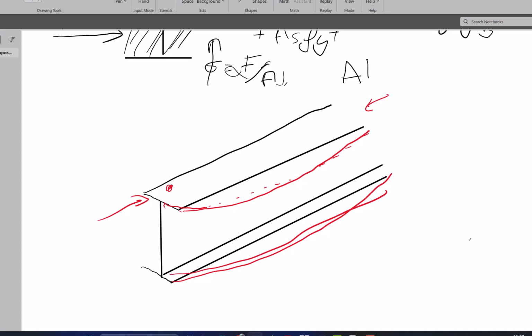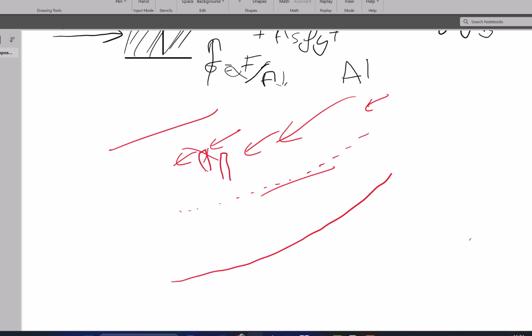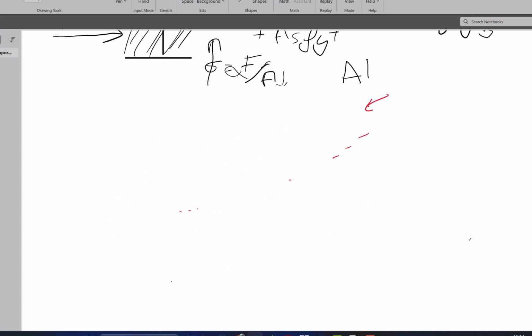Now, if you have shear connectors here, there's a whole design guide on this. What these connectors do is transfer the shear load to the concrete slab. If you don't have these shear connectors connected to this beam rigidly, with the shear capacity to transfer the shear load to the concrete element, it's not a composite beam. So if you think you're putting a deck on top like this, and maybe screwing it like this, that is not a composite beam.